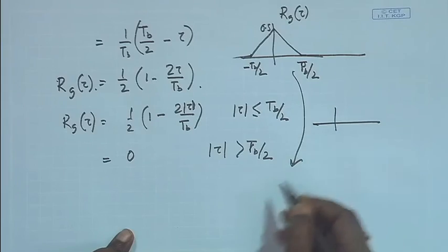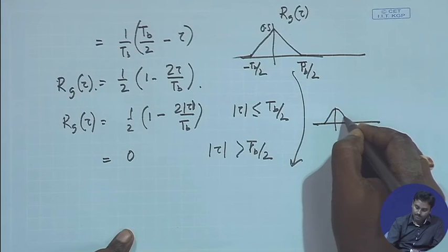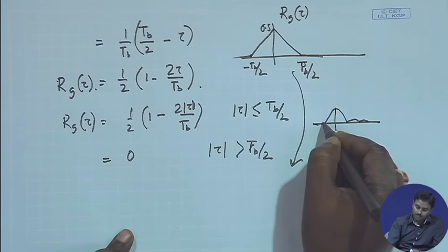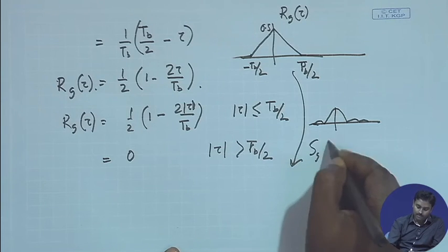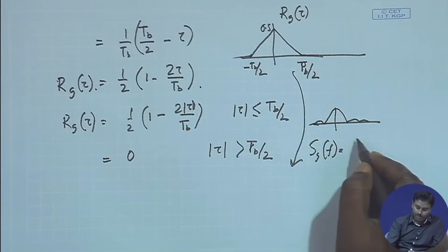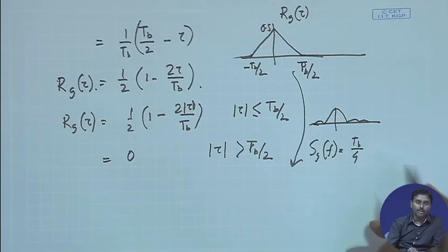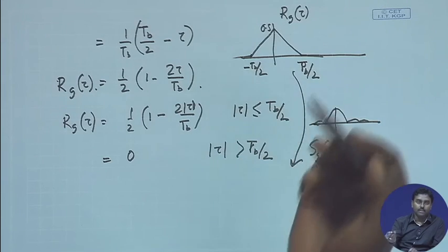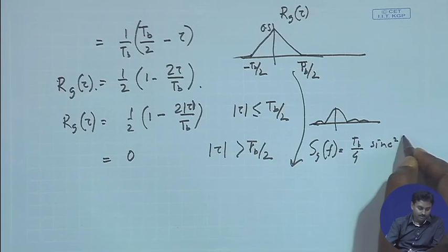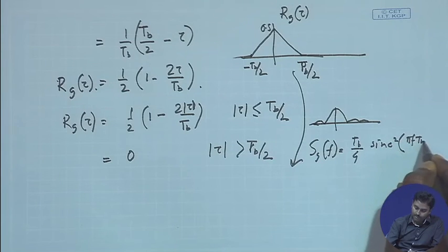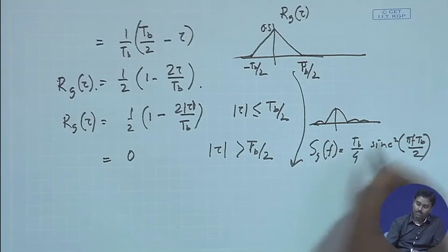Okay. So, it happens to be this, where SGF is actually TB by 4, you can just evaluate that. So, you take this and do a Fourier transform, we will see that it becomes sinc square of FTB divided by 2, and that is the pattern.